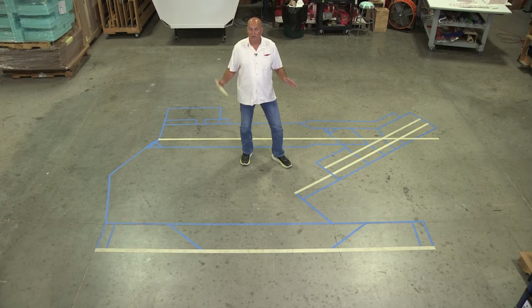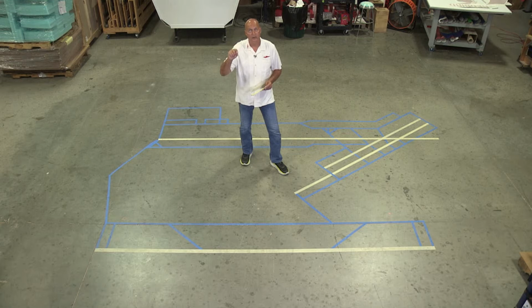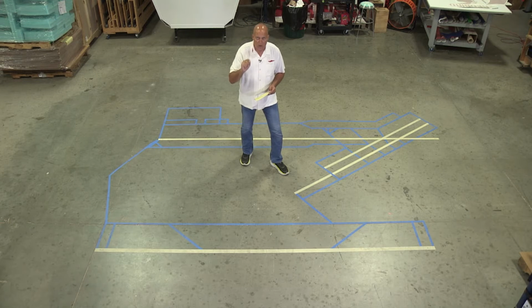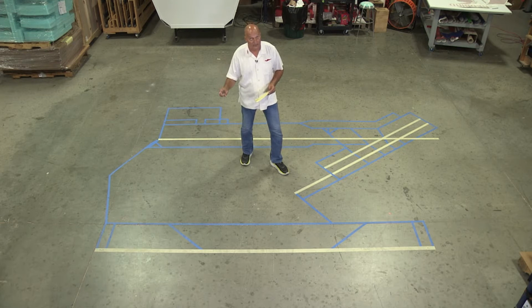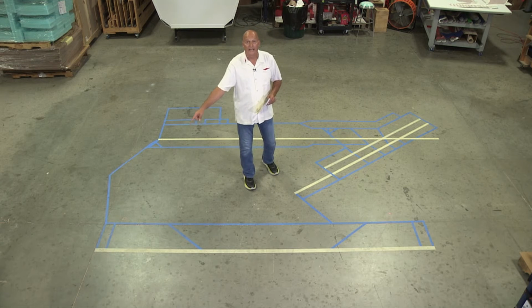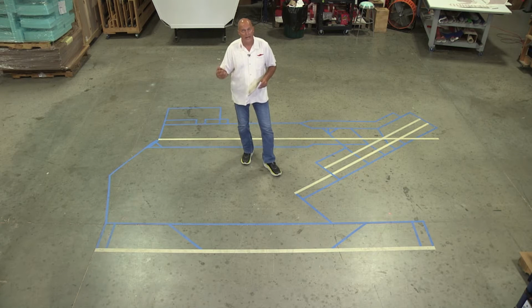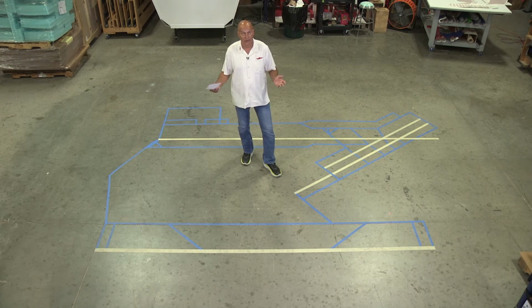So as we stand here in roughly the center of the airfield, we'll take a look and we'll see what type of runways we have, how they're oriented. We can take a look at the width of the runways. For instance, when the students are pulling up those satellite views of an airport, do they know that you can tell how wide a runway is by how many piano keys there are at the end of that runway? So if we look at runway 8 right and you say this is a 200-foot wide runway, how many of those piano keys would you expect to see on the threshold? 16? Yeah, for a 200-foot runway, there you go.